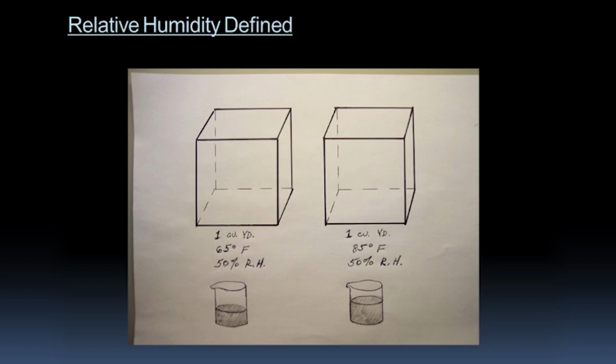And beyond that total capacity, the air becomes saturated with the vapor, and the vapor begins to precipitate out in the form of a liquid. If you're outside, that might be rain or dew, or if you're in an indoor space, that precipitation might be condensation on a window, or it might be condensation on a wood wall panel, which of course is not good, and it's something a lot of us have probably seen. The rule of thumb is that the lower the air temperature, the less water vapor it is capable of supporting, because the air molecules are moving more slowly than they would at higher temperatures.